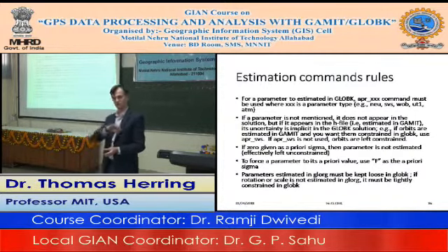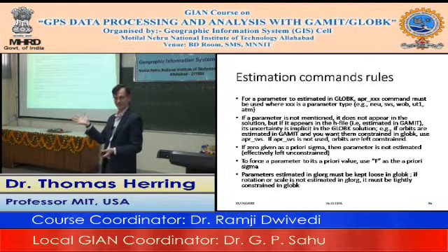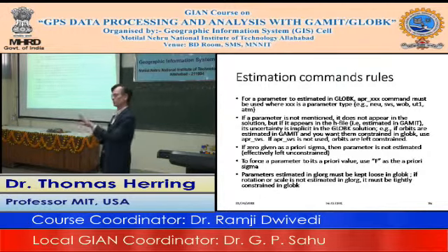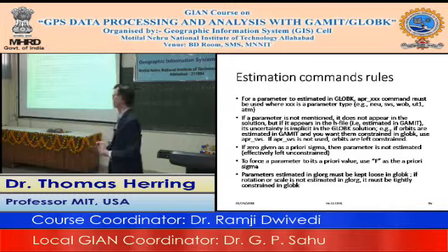And we know that there are these large scale loading phenomena that occur in the Earth. And when you take regional networks, well, it's a pro or con, and you just got to be aware of what you want to do. When you take a regional network, if you're estimating scale, what you're doing is taking out that average height change. And maybe that's what you want to do. But if you don't realize that's what you're doing, it can be a mistake. And so scale is always one of those things you have to carefully think about.